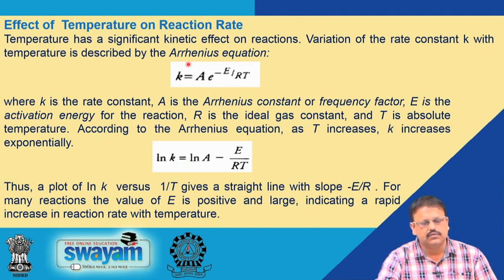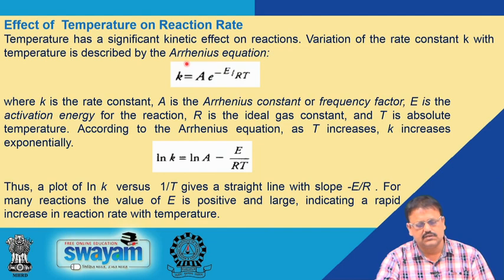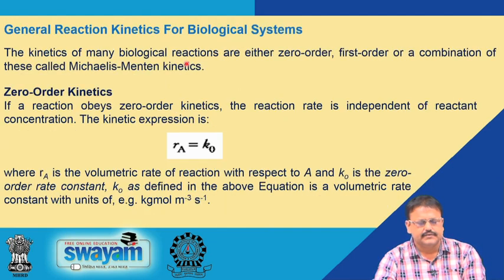So maintaining the optimum temperature is very important from the biological reaction point of view. From the microbial growth point of view, the temperature effect is also very high. If the microbes are growing at 30 degrees centigrade and we increase it to 35 degrees centigrade, the microbes may die fully due to thermal shock. At a lower temperature, similar phenomena may occur and the productivity will be hampered. So we have to maintain the temperature in that specific optimum zone only.